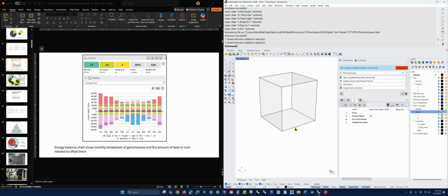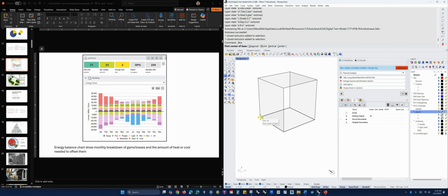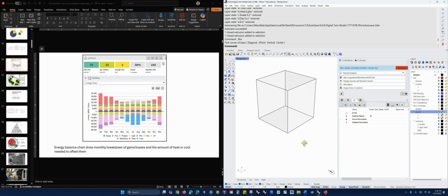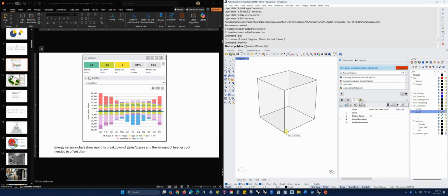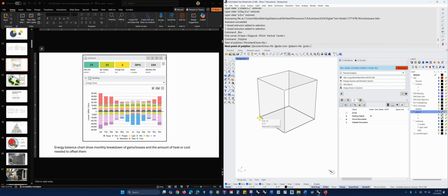And by the way, this just needs to be an extrusion. So if you have a more complex cube that has the thickness of the particle board or the chip board or whatever, you don't want to use that. So just come in and make a new extrusion. You use that as your baseline, and then make an extrusion around that which represents the exterior of your entire cube. Technically it would be the interior, but it doesn't matter. It's a very thin cube. Remember, we're also using the foot version. So this is an 8-foot cube, not an 8-inch cube. 8 feet, right? Okay.